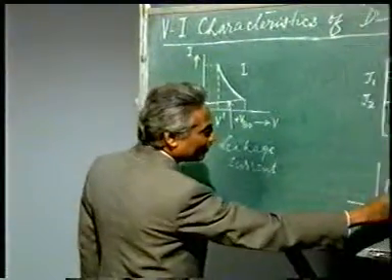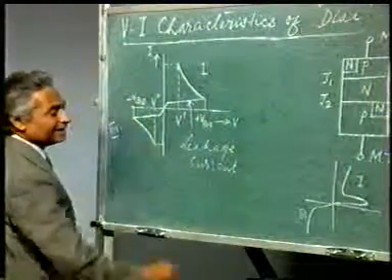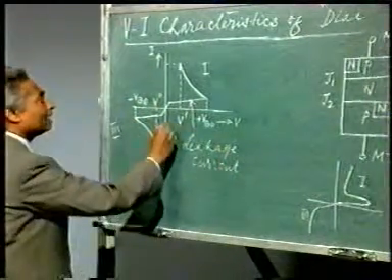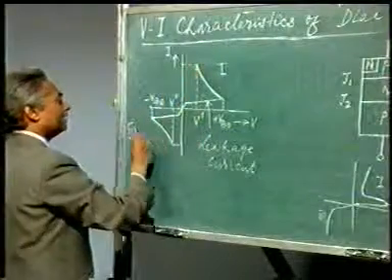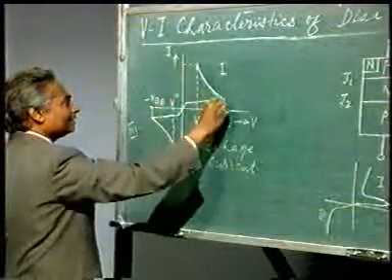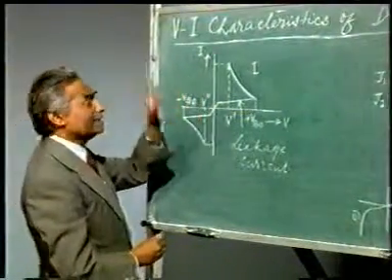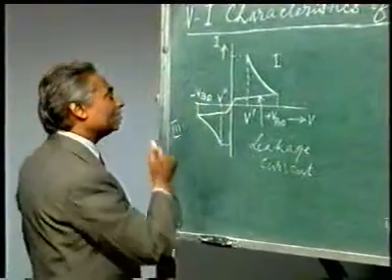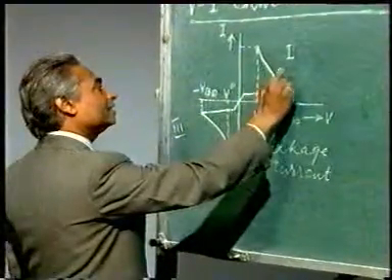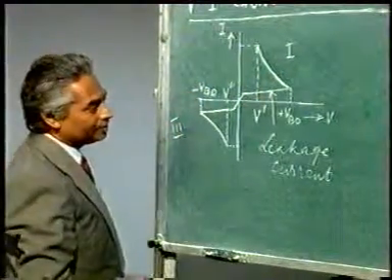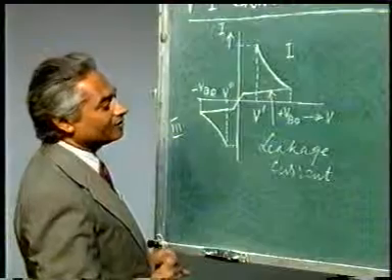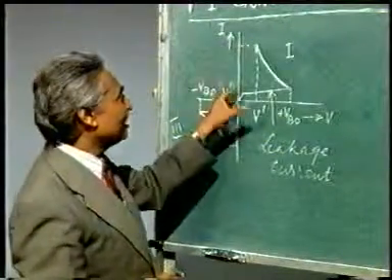When it was forward biased, we say that it used to conduct, and it is known as a rectifier. Here in both the halves, that is the positive half cycle and the negative half cycle, this is conducting in the same fashion. So we can safely connect this device in an alternating current circuit, and it will conduct similarly whether it is forward biased or reverse biased. So this is all about the VI characteristic of an SCR and the VI characteristic of a DIAC.